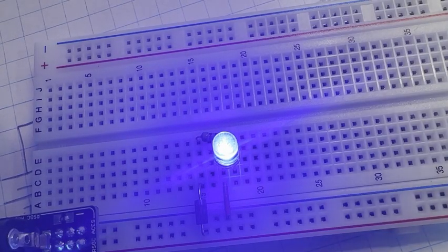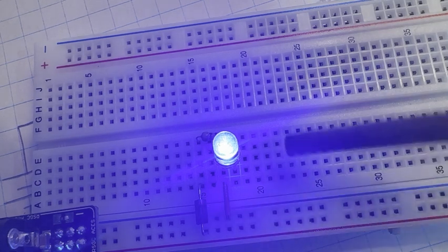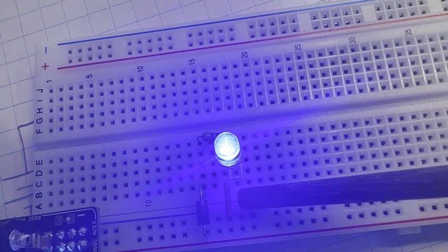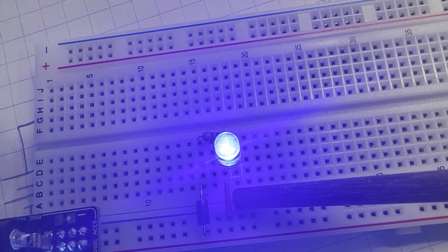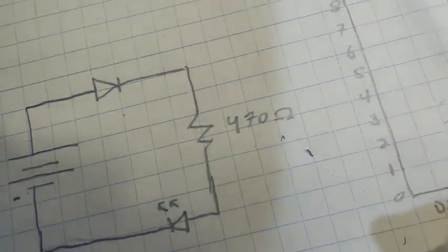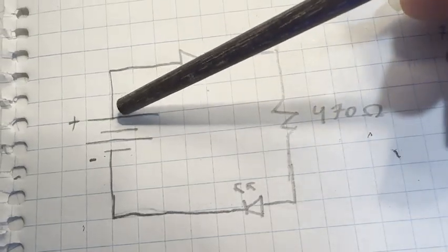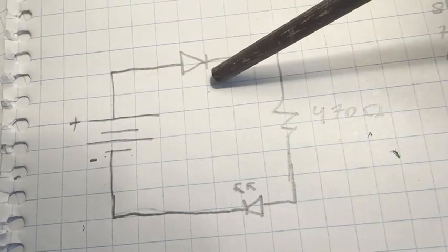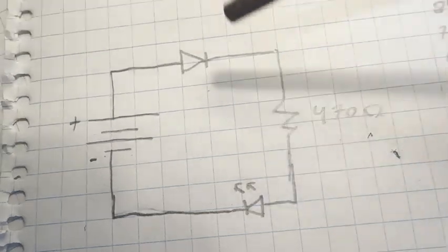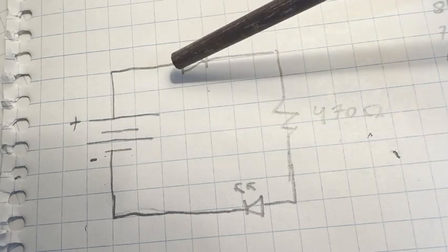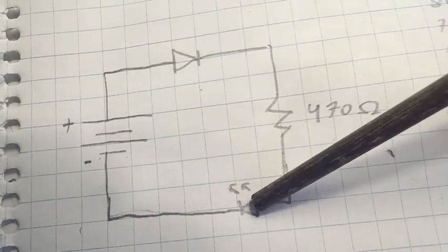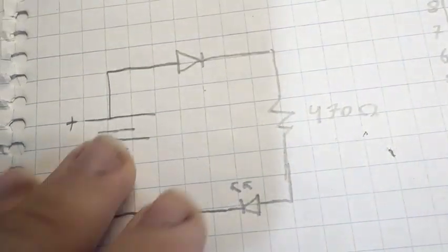This circuit here, consisting of one diode, one 470 ohm resistor, and one blue LED, along with an orange 4/10 of an inch wire, follows this circuit diagram here, with this being the diode, this being the 470 ohm resistor, and this being the light emitting diode. Through this circuit, you can see that the current can only flow one direction through this diode, flows through the resistor, and can only flow in this direction through this LED, in turn lighting it up as blue.